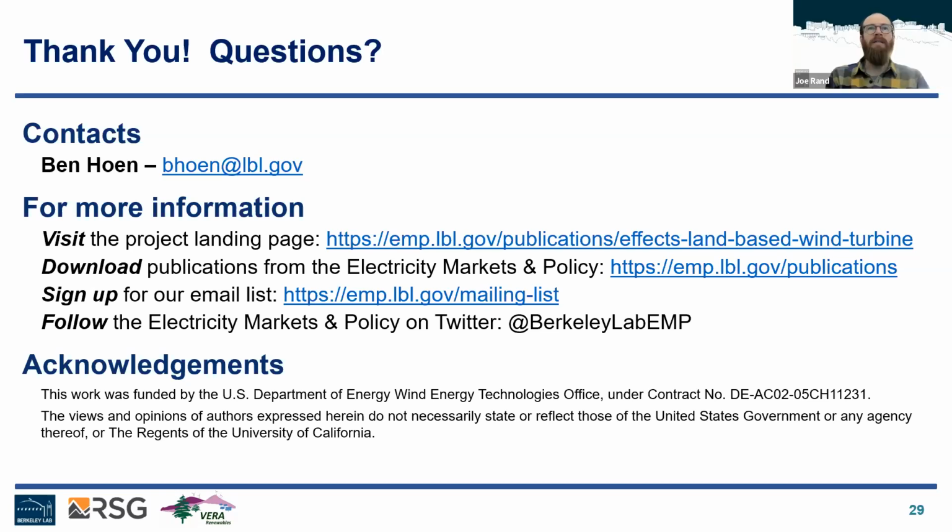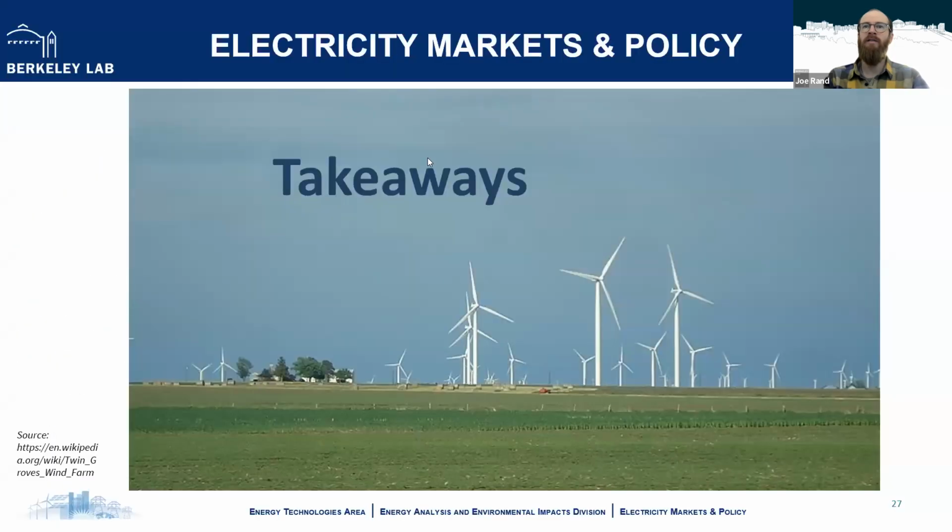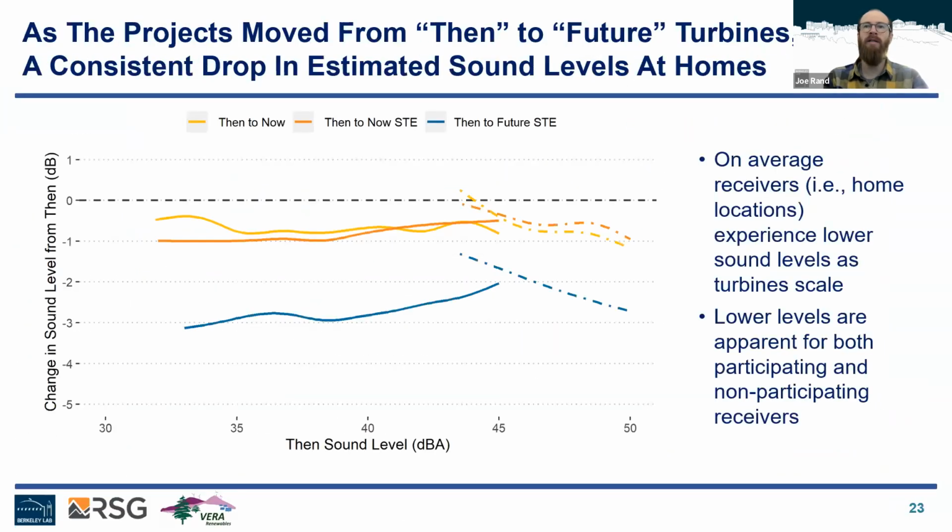All right, I propose we move to the next question. So yeah, I think there's a great question here talking about amplitude modulation. As turbines get larger, we potentially have greater wind shear, or the difference in wind speed across the rotor that might be more prominent with larger rotor diameters. Could that lead to greater modulation in the sound, while still having the turbine placement and the receivers being under the decibel limits that are enforced?